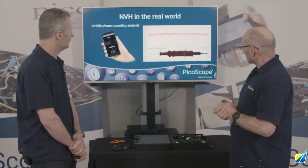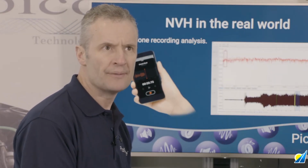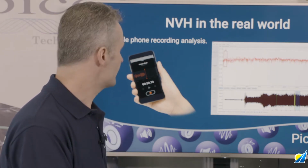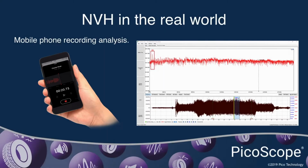So here we've got an audio recording. You can see it's been imported into NVH. There are two markers there because I know between those markers is where I can hear this noise. Obviously we don't have engine speed or road speed, we have nothing but raw audio data. But if we ask our customer for some key answers, such as what was the engine speed, do you know what road speed you were doing, do you know what gear you were in, we can start picking out key frequencies amongst these peaks. And here we've clearly identified E2 based on the recording from the customer, who's told us the engine was at about 1700 RPM in this case.